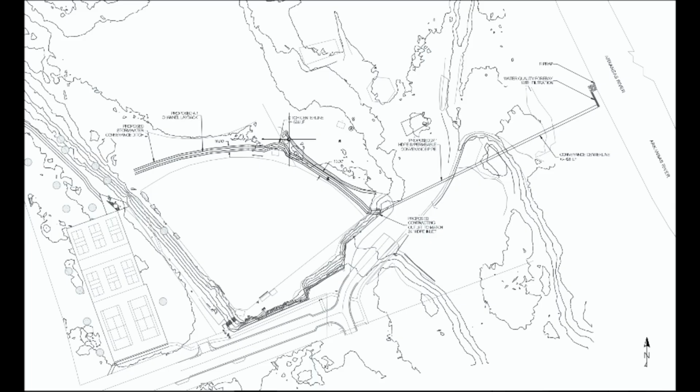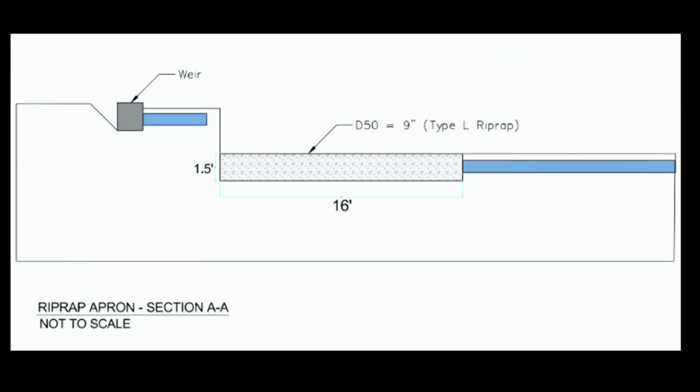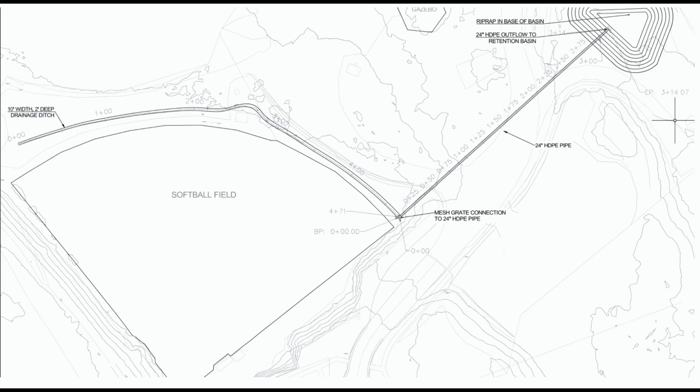Alternative 1 uses a 524-foot open ditch combined with a 426-foot pipe system. This leads into a forebay with riprap, which filters the water and slows it down. This allows the water to be dispensed into the Arkansas River. Alternative 2 uses a basin using the same ditch with a 314-foot pipe to move the water into a 1-acre basin. This then will get drained into groundwater over a set period due to the infiltration rate of the soil.